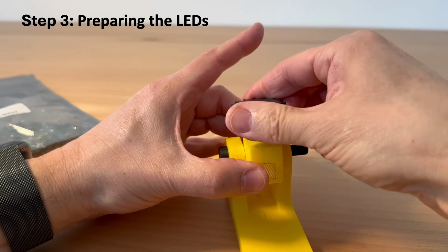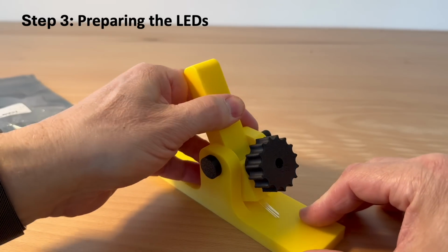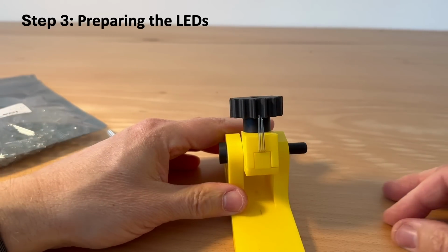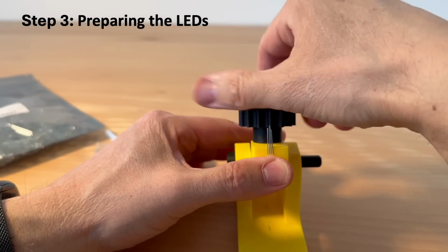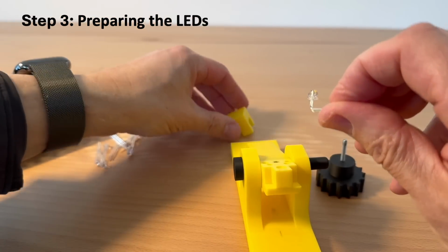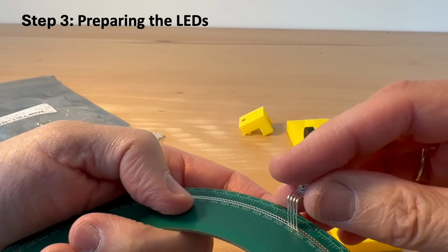Keep also in mind that the orientation is mirrored between the left and the right side of the board. This is due to the interlacing pattern. The LEDs need to be aligned identically when the board rotates 180 degrees. So now we can have a look at the bending result. And once the LED is properly bent, it can be soldered into place with ease.